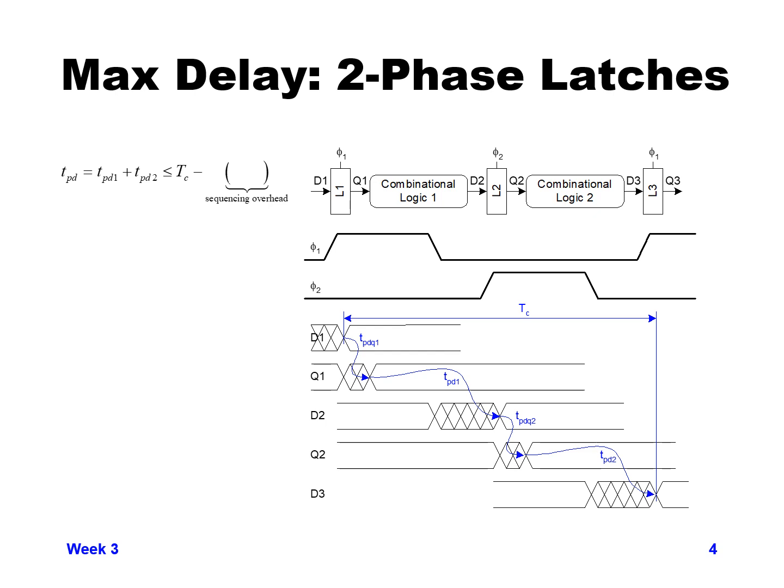We want to design it ideally so that each phase of combinational logic together takes up one cycle's worth of time. So we try to fit an amount of logic in both sets of combinational logic to get one cycle's worth. And one cycle is from when the first latch L1 opens to when the third latch L3 opens. So we have the logic going through two different phases.